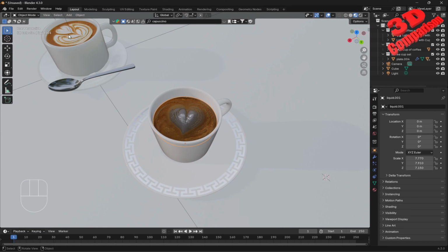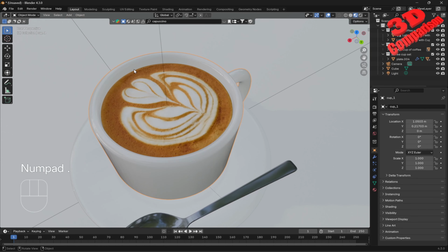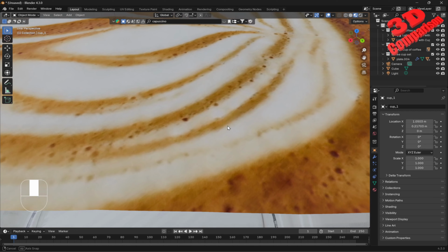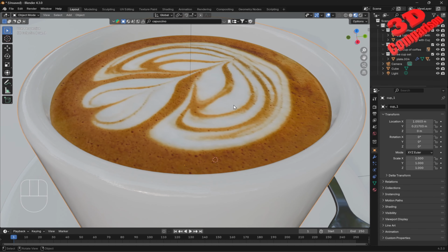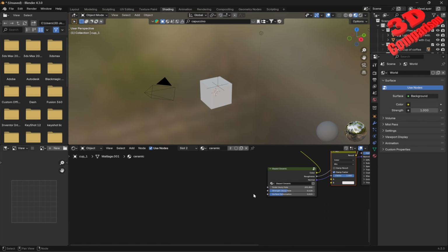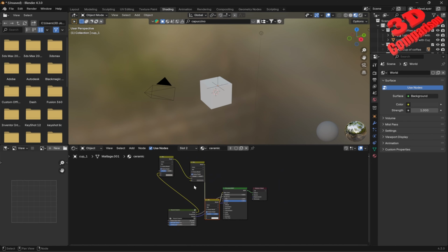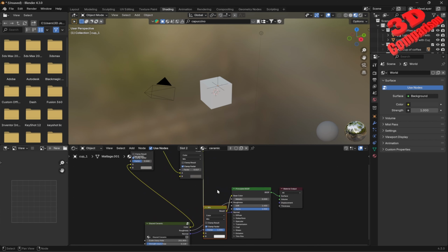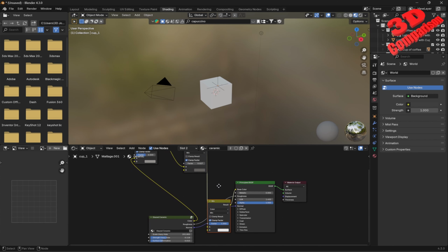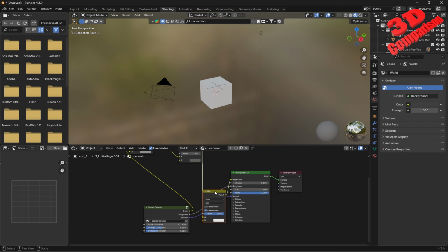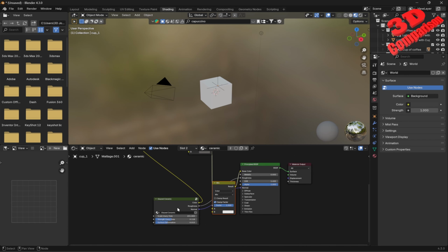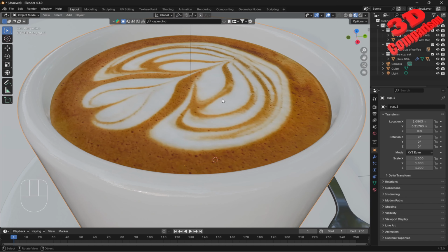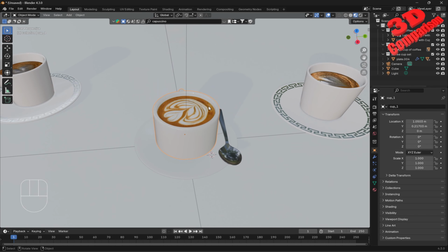Let's just check the other assets. So for example, we see that this one, the texture will look a lot better even from a close-up, and it will have a little bit of displacement. If I go to the shading, we're going to see that this material will be different. So it will not have the classic displacement. In this case, we'll have some mixing. So as we can see over here, there will be those mixing and with the ceramic texture over here. So actually this will not have any depth map.